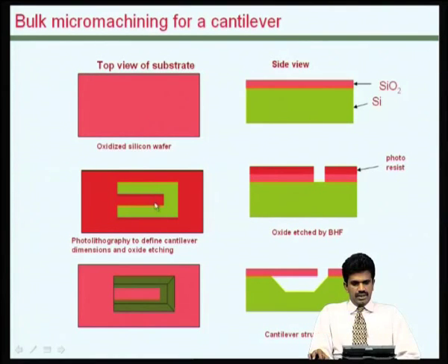What happens while etching is that when we form this surface, let us say we use outside as the etch window film, we create this cavity, the hole here in the etch window, but as the etch progresses, what would happen is that a 111 plane would get formed here as well as here.